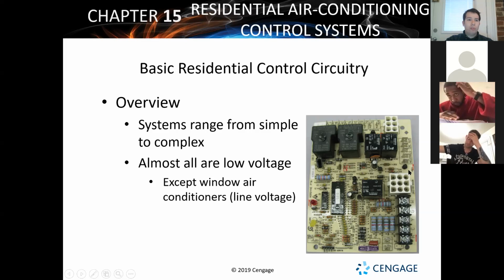Those are all for neutral. It's called your neutral bus, all right? And it just means that your neutral terminal or neutral bus terminal, because much like a bus and an actual bus station, this is basically where everything comes together. This is where they all meet up and they get back to one spot. And so we have a location where it's going to be all these neutrals.